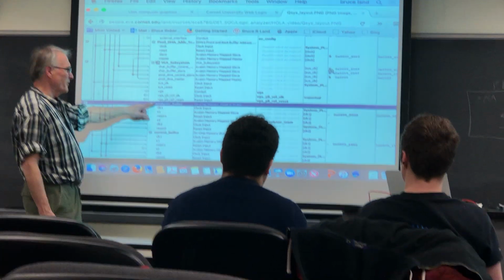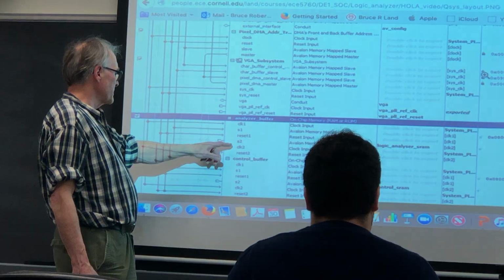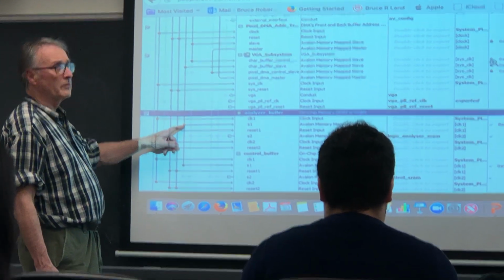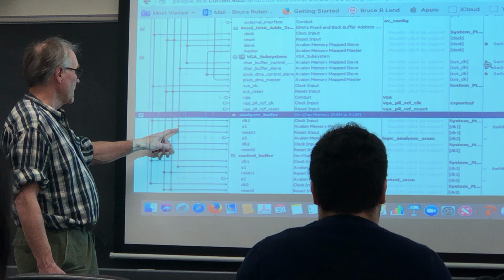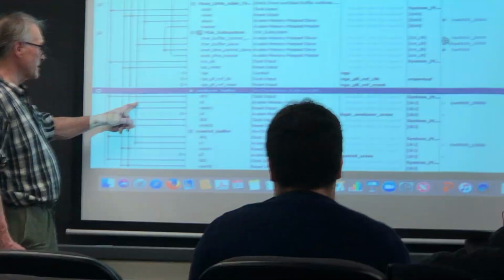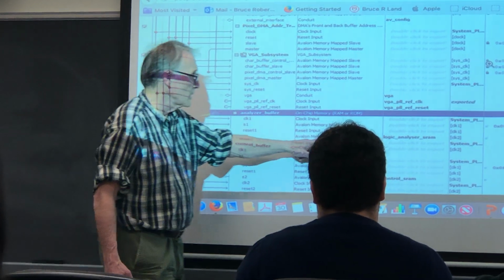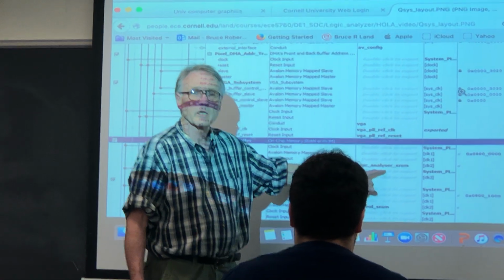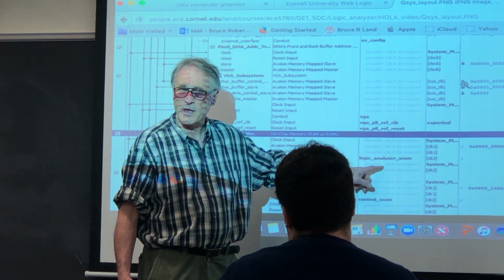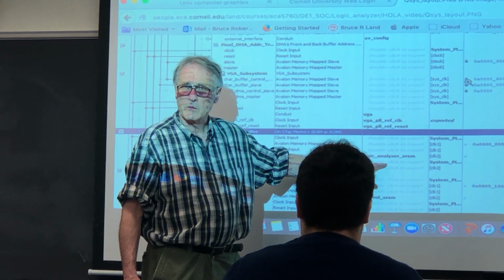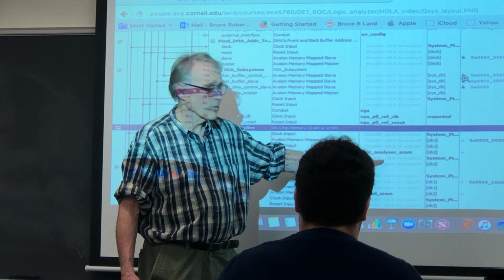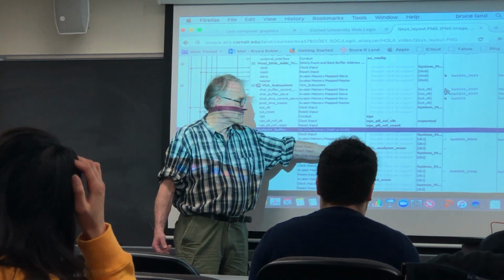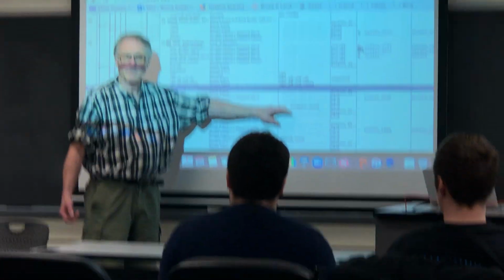So the analyzer buffer here is on-chip memory. It has two slave ports. One is hooked directly to the Qsys master, and the other one is exported directly into the fabric, so you can connect an arbitrary signal to that to be logged into memory. So there's two ports, one on the bus, one not visible from the bus, but it is visible from the FPGA.